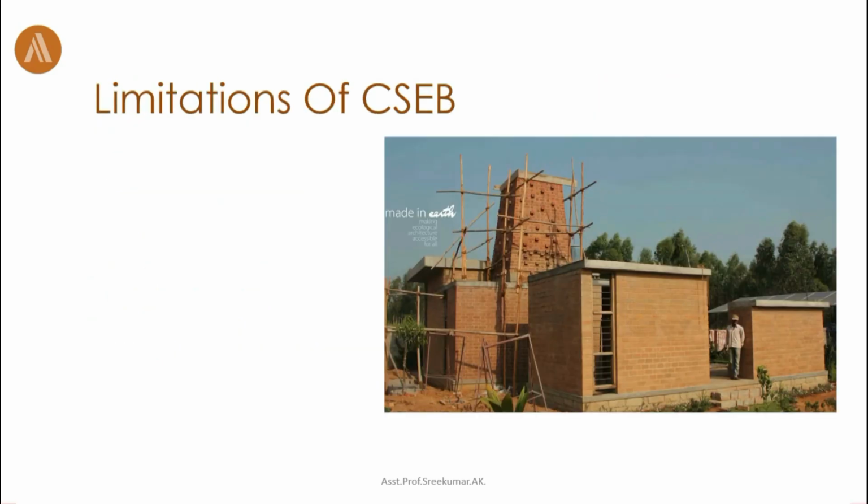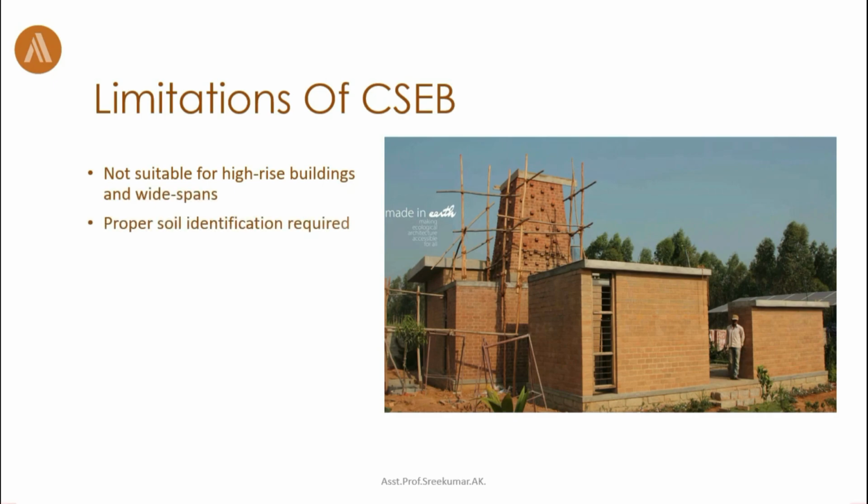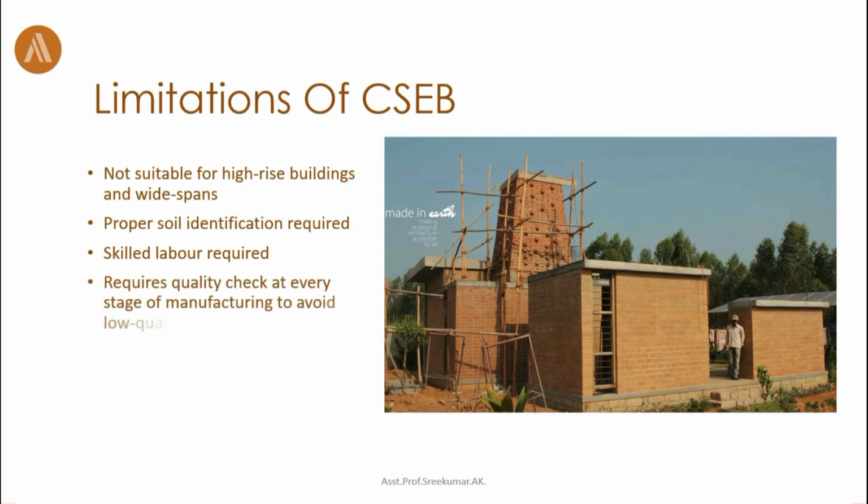However, there are some limitations for CSEB. First, it's not suitable for high-rise buildings and wide spans. Second, proper soil identification is required prior to the construction process. Third, skilled labor is required. Fourth, it requires quality check at every stage of manufacturing to avoid low-quality products.